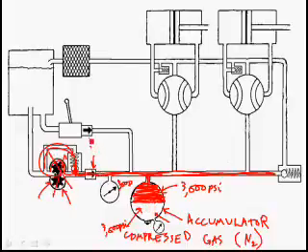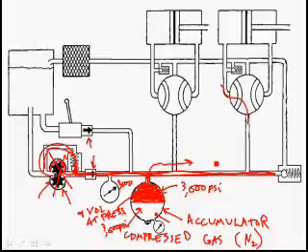We've got the check valves, so fluid can't get out, but look what we're doing right here. We're storing a volume of fluid at a pressure. So that means we have hydraulic energy stored up inside of this accumulator. Now we could rotate one of these selector valves and fluid could leave the accumulator and fill up this side of the actuator.